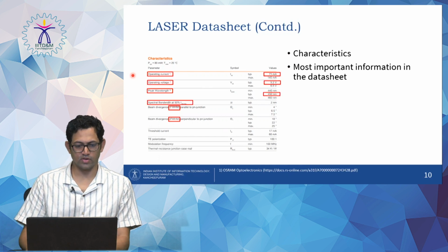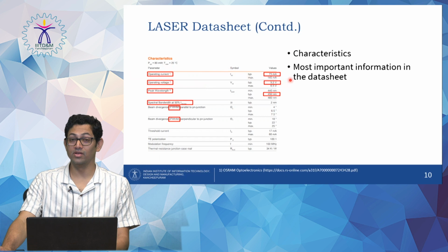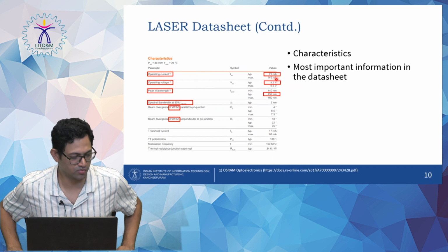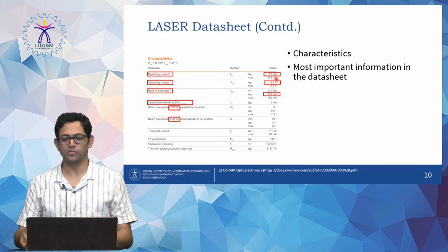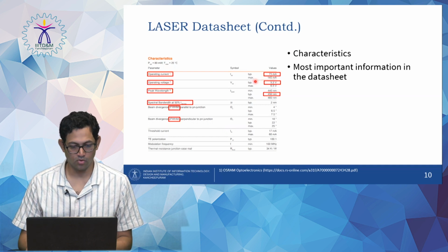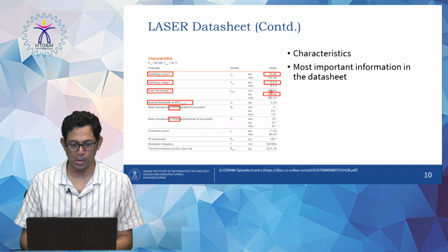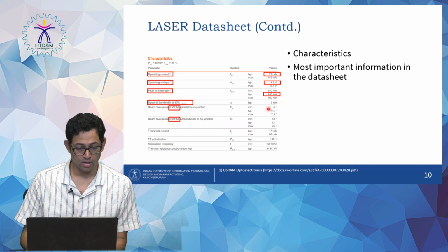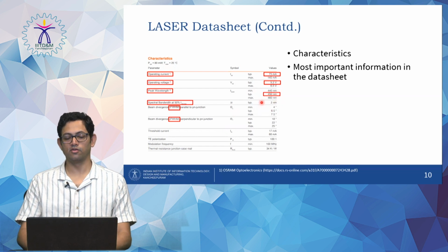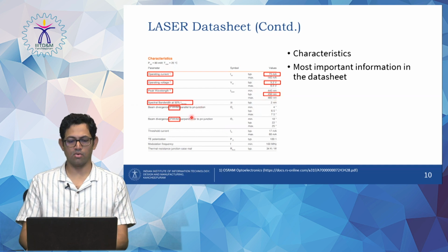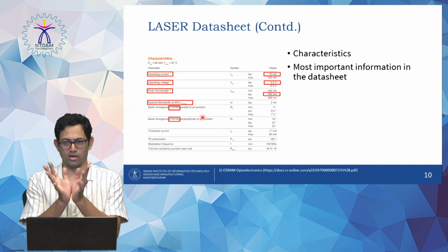So here you can see that we have operating current. Typically we need to operate around 75 milliamperes, right. Maximum is given as 145 milliamperes, so we should not actually operate more than that. Okay. We have operating voltage, typical around 5.2 volts, maximum 6.5 volts, and then we talk about the peak wavelength, which is around 450 nanometers, that is the blue light. And then the spectral bandwidth, that is the delta f or delta lambda, and then we talk about the viewing angle as well. Okay.